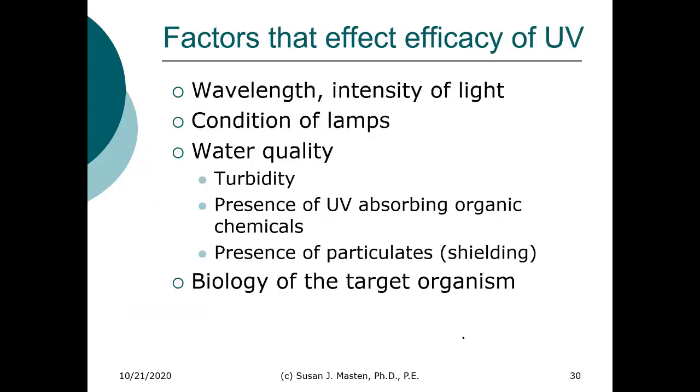In terms of factors that affect it, most of these I've really mentioned, but wavelength also affects it in terms of the energy, the intensity of the light, and the condition of the lamps. I talked about not having growth of slime or chemical deposits on the lamp. And then the ability for that light to actually be transmitted through the solution is extremely important.